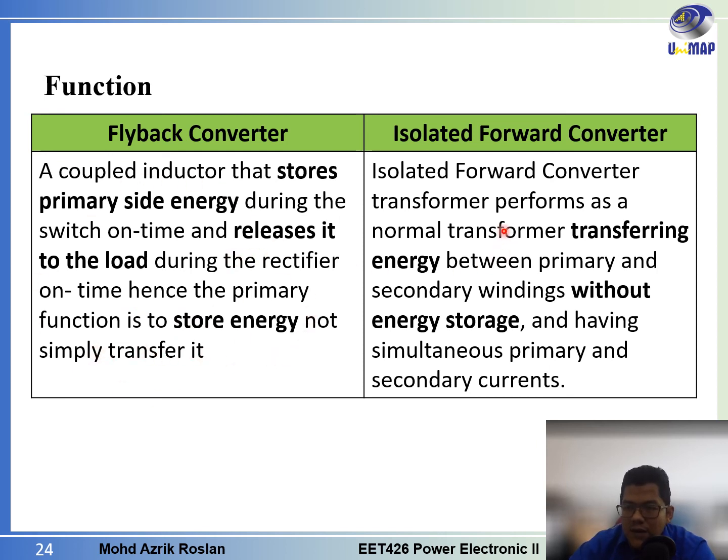But it differs from the isolated forward converter. In the isolated forward converter, when we have the switch on time and we supply the transformer primary winding, the energy is straight away transferred to the secondary winding, without the need for energy storage.